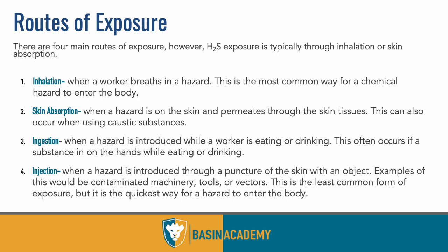Routes of exposure for both gases. Inhalation is the most common, by breathing it in because it is in the air or mixed with the air to some degree. Skin absorption can happen if it's in liquid, typically. If you're a water hauler, an oil buyer, a roustabout, or someone who's cleaning tanks, it's possible to get it on your skin. Ingestion is the same kind of method: if it gets on your clothes and then onto your skin and into your mouth. Injection is not as common, but that is a chemical exposure. If you're using a pressure washer and somehow the grease and oil that has SO2 in it gets punctured into your skin, it could happen, or on a sharp object, but that is a little bit less common.